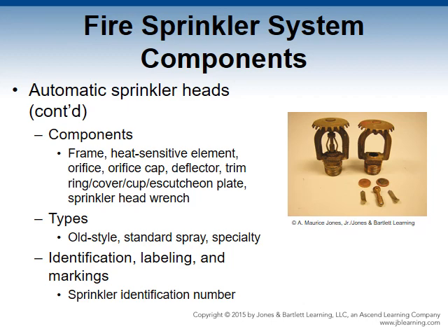You have a deflector, which can be seen here, and that breaks the water stream into smaller droplets and forms a relatively even distribution spray pattern. They can be trim, ring, cover, cup, or escutcheon plates. They appear to be only decorative, but may be required as part of the listed ensemble to meet fire resistance rating for the ceiling or wall.